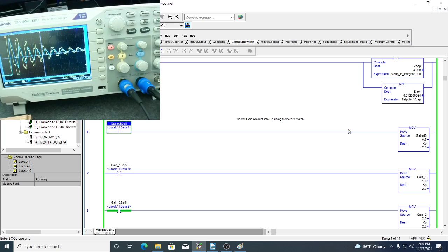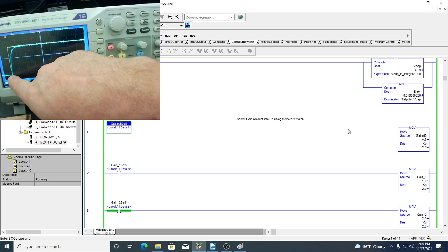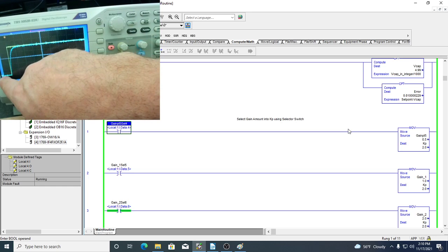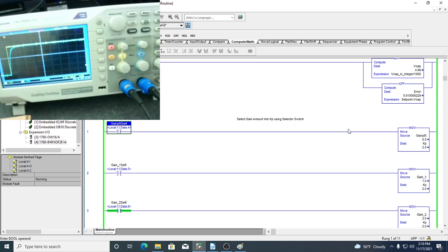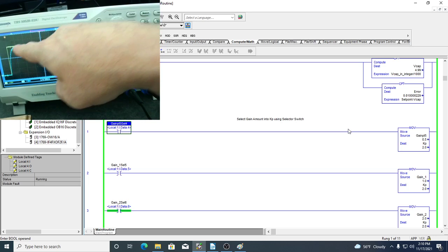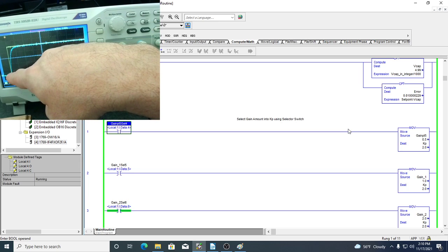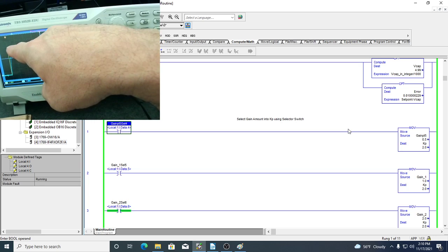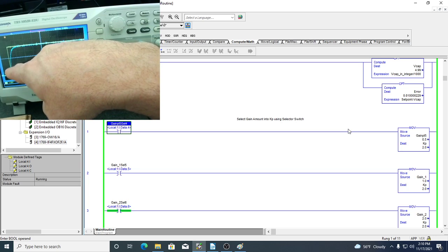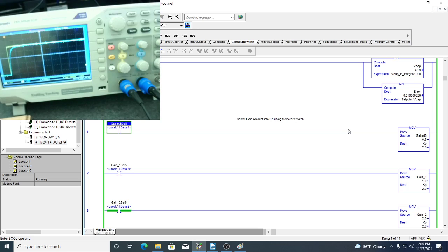It's going to take about 10 seconds to display it, and you can see here it has very little resistance. You see the yellow is the step response. So we go up from 0 to 5 volts. The yellow is immediate because we're doing no control. We're just outputting. We're saying we were at 0. When I flipped the switch, it went to 5 volts. The blue is the charging of the capacitor. Now again, I had the switch set at 50 ohms, so it charged very, very quickly because there was little resistance.